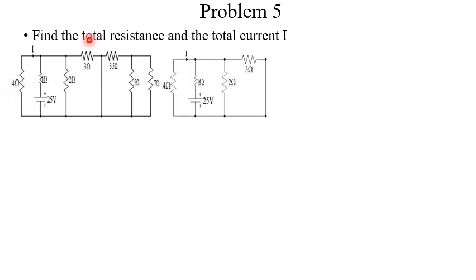So our circuit is given to us here, but when we observe the circuit critically, we realize that there's a short circuit somewhere. So we realize that the 3.5, the 5 ohm and the 7 ohm are short circuited because when current starts to flow from this 25 volt source, it gets to this junction, but when it gets to this junction, it realizes that there are resistances here, but there's a free path here for it to pass and come back. So it just decides to take this free path all the way back. So basically, when we are analyzing the circuit, this 3.5, 5 ohms and 7 ohms wouldn't be added.